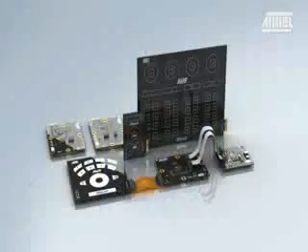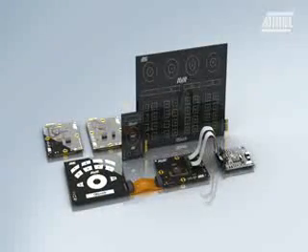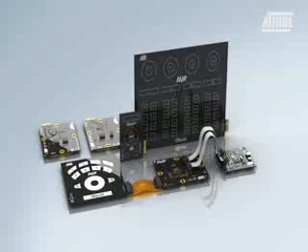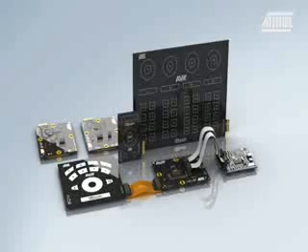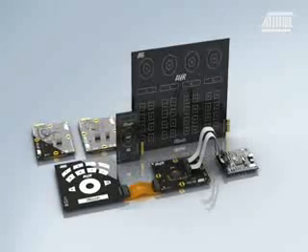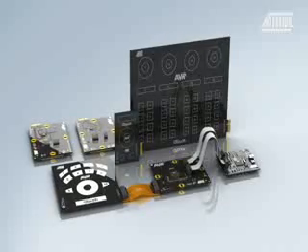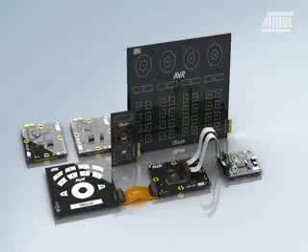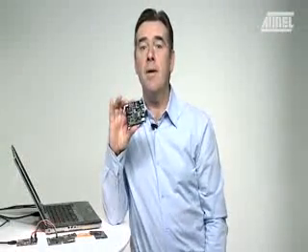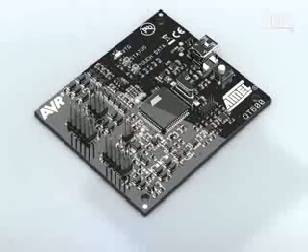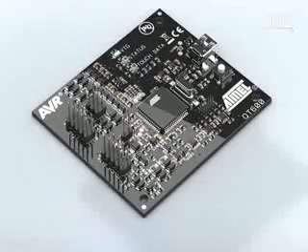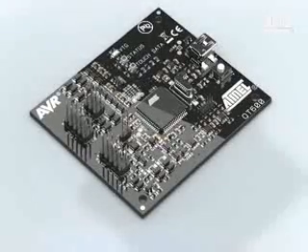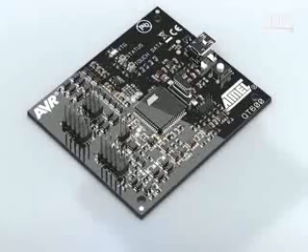In the box, you'll find a controller board, 3 generic target modules with a Mega AVR, Tiny AVR or XMega device, plus various control surfaces with buttons, sliders and wheels on them. The most important part of the QT600 kit is the controller board. This programs your target device, streams QTouch data from the target processor and takes care of the USB connection to your PC.